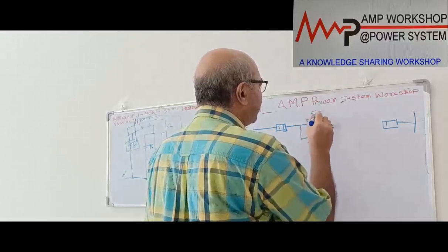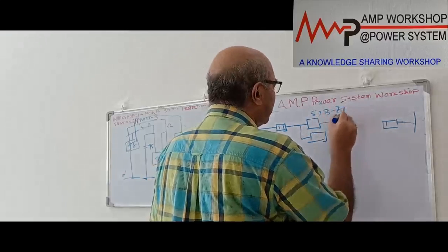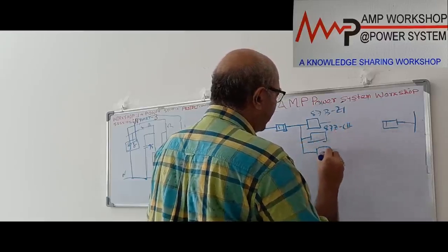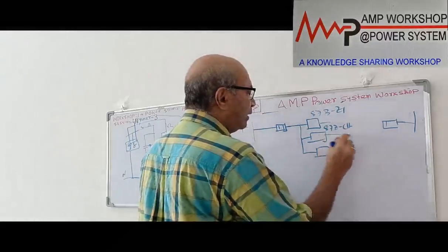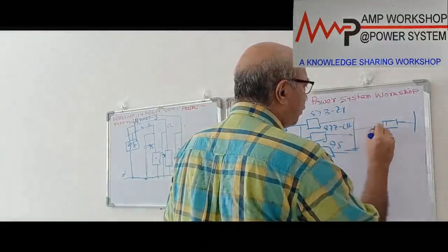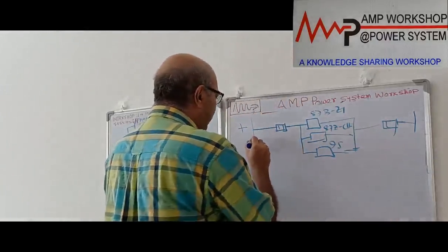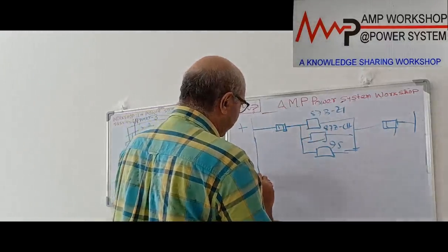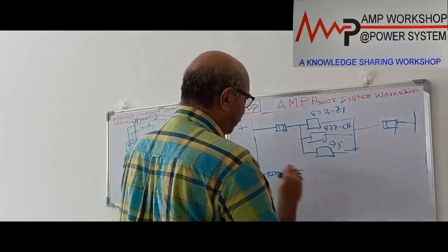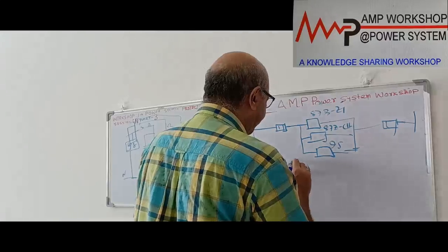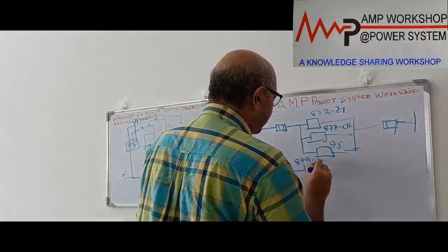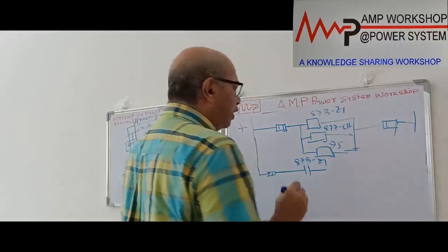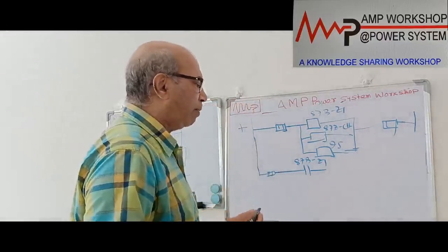Whatever they are, suppose it is 87B1, 87BZ1, then the 87Z check, then we have the 87/95 relay, that is a CT wiring relay. All these relays need a DC supply, so we will connect over here and it goes to the DC. That is the relay power supply. Then what will we do? When this relay operates, suppose 87BZ1 is operating, you can put a fuse over here. Suppose this is 87B1, 87BZ1. When this relay has operated, then what will happen? It will operate a lockout relay, right? We have said already it will operate a lockout relay.